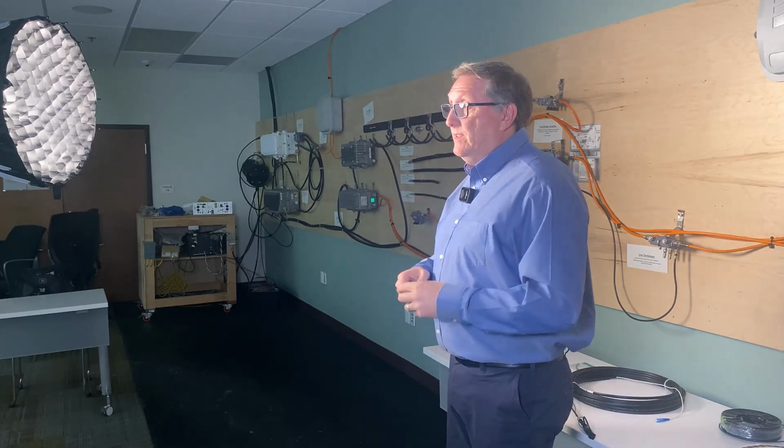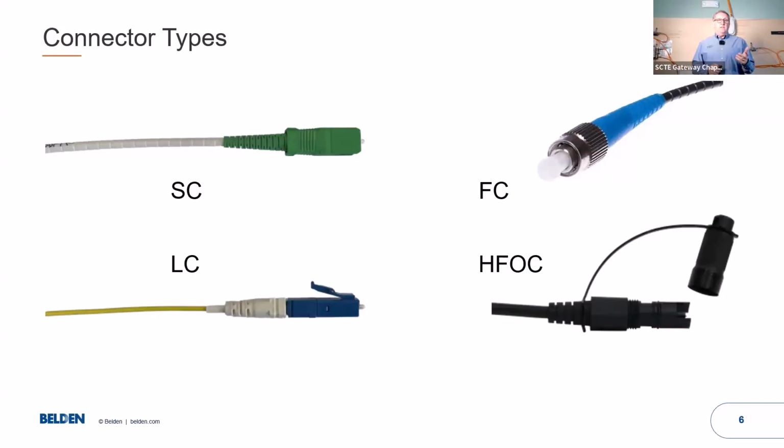When we get to talking about some newer ones, you're going to find out that there are other connectors, an MPO connector, one fiber connector that has between 8 and 24 fibers inside of it. That takes a different type of pen. Smaller ones, an MDC fiber that's used in muxes, has a different kind of pen. So always be aware of the type of connector you have, the type of cleaning device that you need for it, and if you can, the right kind of tip for your fiber scopes to make sure they are clean.